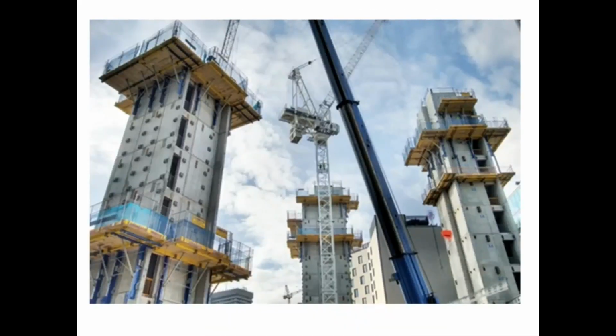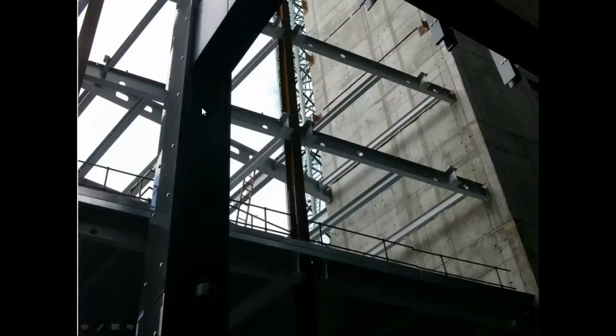The way we tend to do it, particularly in tall buildings, is to have a very strong core to those buildings and allow the building to wrap around that core. In most cases it's fair to say that these cores are made from reinforced concrete. What you're looking at here is, of course, a lift and stair shaft, and it also carries services up and down the building, so it functions in that way. But what you end up with is four big shear walls which are acting like continuous columns in the pinwheel that we looked at earlier on, that give an enormous amount of stability to the center of the structure.